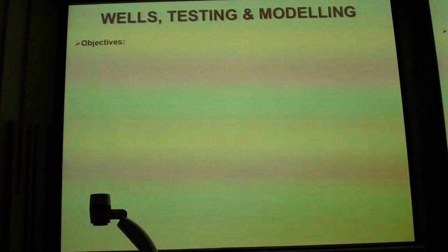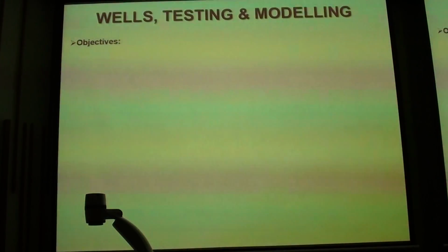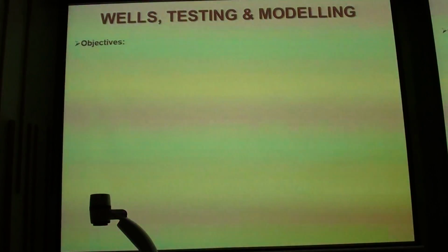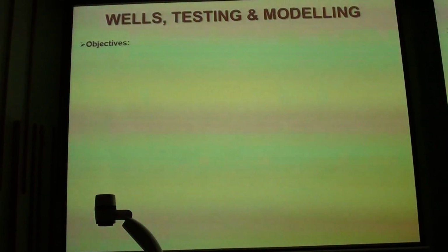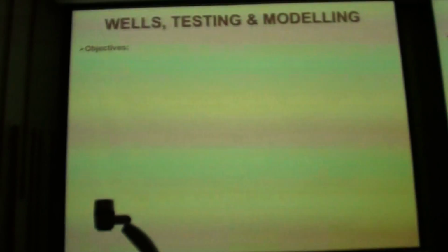Okay, so we've gone through the process of drilling a pilot bore, just a narrow diameter hole into the ground. We've got aquifer material, which we've assessed, and we've decided we've got aquifer, so we've cemented that pilot bore in place. Before that we did a few tests on it, displacement tests, with the falling head test, worked out approximate hydraulic conductivity, and decided everything was okay to proceed.